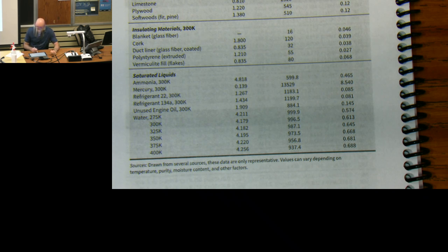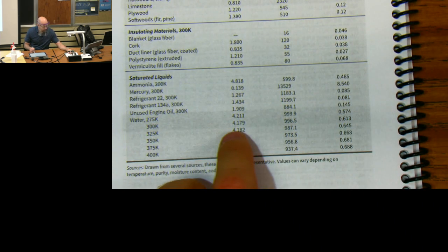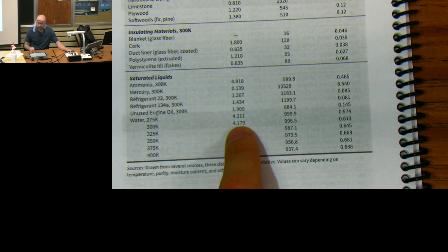Secondly, 46.6 is about 319. So using the value for 300 Kelvin as my specific heat is reasonable. If I got this answer to be, again, 400, I would have had to then go and iterate and say, that solution is probably not good enough. I need to go back and pick a different value for my specific heat. Now, if I would go back now and say that 319, and come up with a different C sub P value, a more accurate C sub P value, my answer might be 46.58, and that's not worth the effort.